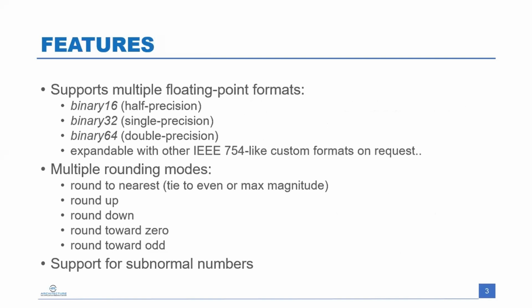What are some of the features that we can say about it? It supports multiple floating point formats that are needed for today's computation. It has all of the required rounding modes. I would say rounding modes are quite tricky because they take a significant amount of area if you want to implement them correctly. We have seen a lot of designs that do not calculate things correctly when we come to some of those corner cases, and of course it supports subnormal numbers.